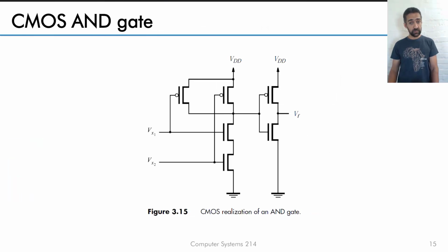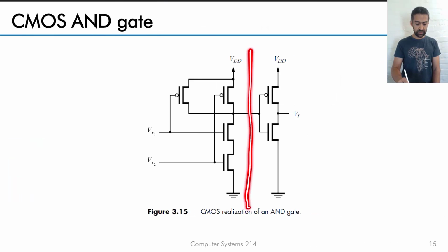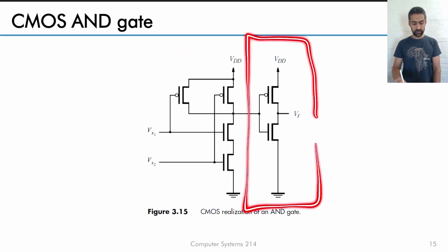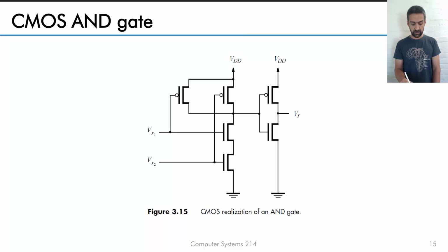You can also do a CMOS NAND gate, and again, it's just a NAND gate and a NOT gate that provides that input. And again, the input impedance here is high because it's a field effect transistor, which means there won't be any current, or very, very little current, flowing in that direction here.